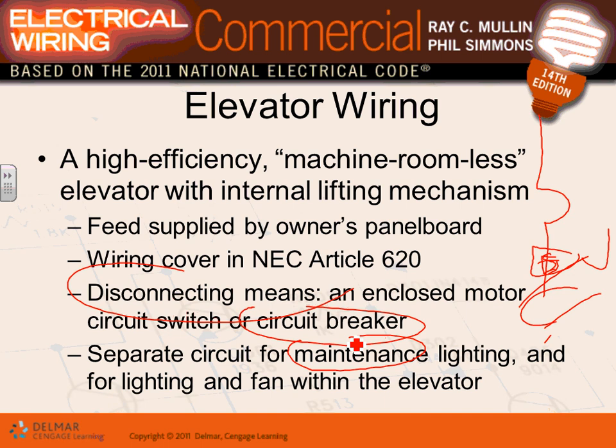So you need a circuit for the car. If you guys walk into our elevator right here, what do you see? You have a light and a fan inside the elevator. So they give a 20 amp circuit typically for the light inside the elevator car, a 20 amp circuit for the fan inside the elevator. And in the machine room, they typically have a 20 amp circuit that feeds GFCI receptacles. So these are dedicated to the elevator.